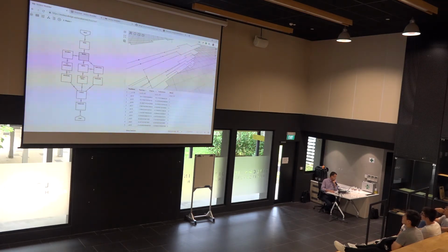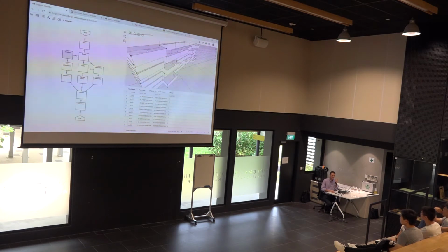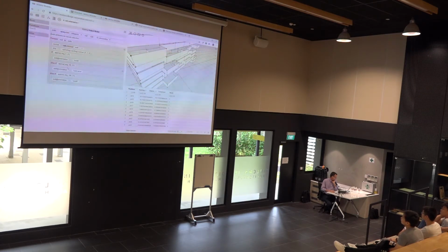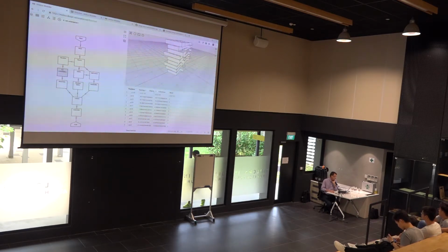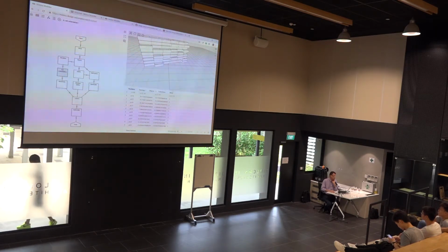On the other side of the floor, you're doing the facade. So here we extrude the floors into facades, just polygons. Again, you keep the nodes so that it's simple at the beginning and gradually gets more complicated. Then you do a... I've forgotten what we did there. So we don't want to have windows on these facades, right? So we don't want to have windows here, we just want to have windows on this side.